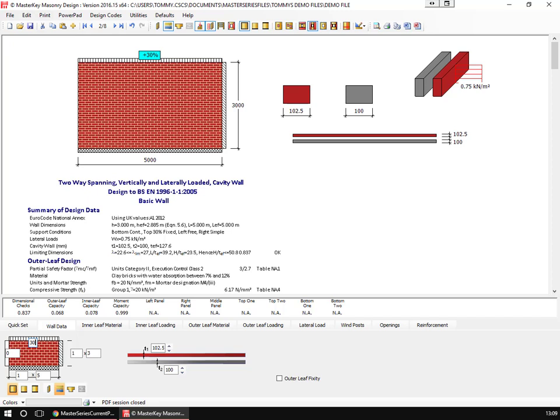Obviously, these degrees of fixity all come from the simple equations, and it's up to yourself to decide how fixed it is. I would never be considering it to be 90% fixity, because it's either fixed or it's not in that respect. But 10, 20, 30% fixity when you're coming into a wall and shot fixed against it and there's virtually no movement, absolutely. Normally with shot fixed, if there's no movement, you take it as fully fixed. But if they do have some backing material, then you can take a degree of fixity just to get that bit more of restraint.